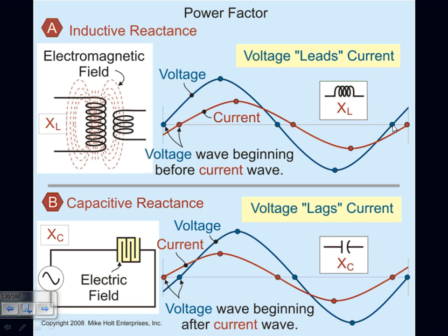Leading power factor, lagging. This is one of the most important things. If you walk into any building, and they ask you, is it leading or lagging? 99.9% the building is what? Lagging. How much lagging though? Is it lagging by 95% power factor, or by 90% power factor, which is up to this point, 90%, 95, good? Or is it lagging by 85%, which is not that good, or 60%, which is miserable?